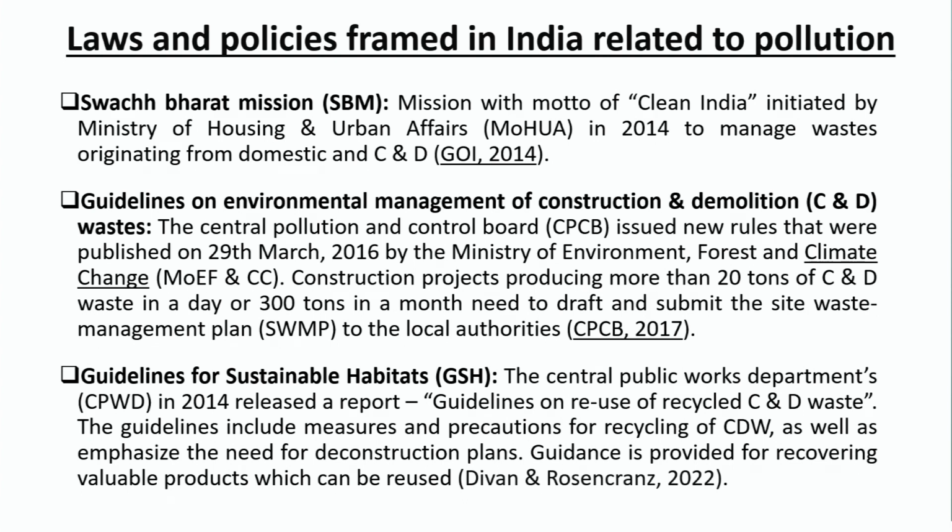Next, guideline on environmental management of construction and demolition waste. The Central Pollution Control Board issued new rules that were published on 29th March 2016 by the Ministry of Environment, Forest and Climate Change. Construction projects producing more than 20 tons of C&D waste in a day or 300 tons in a month need to draft and submit the site waste management plan to the local authorities for their approval.